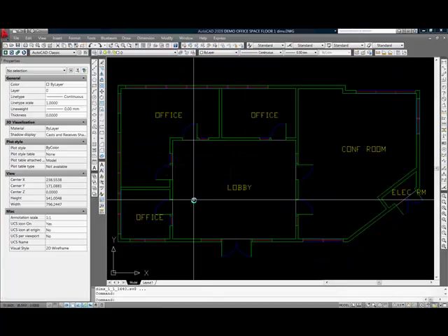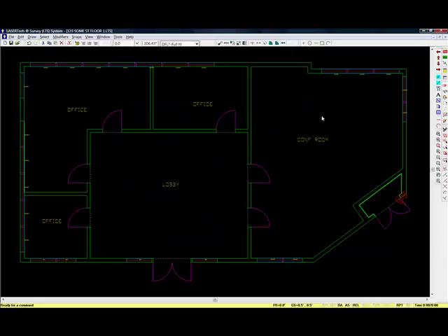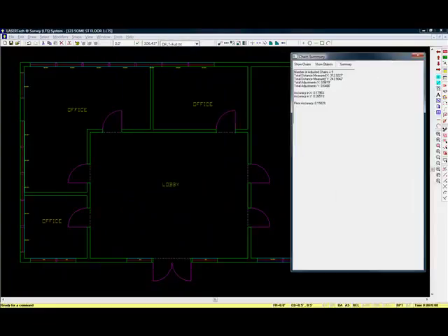And we go back to AutoCAD, and you can see we have everything, and we'll bring up some statistics on the drawing. The system is keeping track of our accuracies. It shows me that our overall floor accuracy is 0.1582%. There are 9 chains in the survey. That's the total length. The total adjustments in X, about a half a foot, and the same in Y, approximately 0.64 feet. And so the overall accuracy is plus or minus 0.15%.